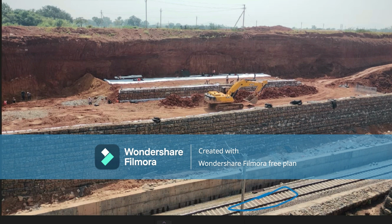Here we see the track level into the blast, and then the pump or drain down the track level downside, and the wastewater there has boulder packing. Every gabion box is 0.5 meter in height and the slope is at a 6 degree angle. They constructed the first berm of the slope, and each layer is provided with the geogrid, and along the vertical layer the geotextile is provided. Here the second berm will be constructed at some distance. The second gabion block starts.